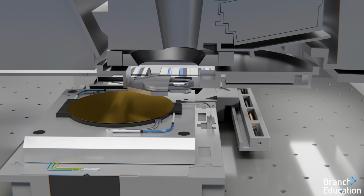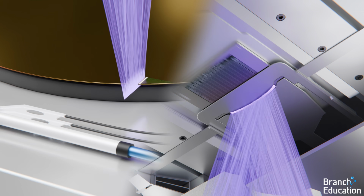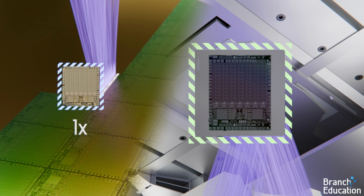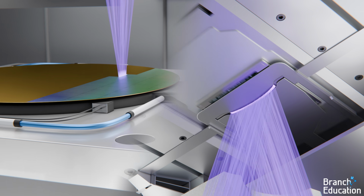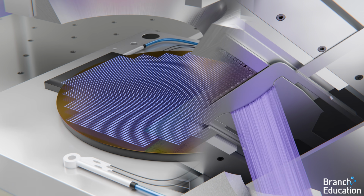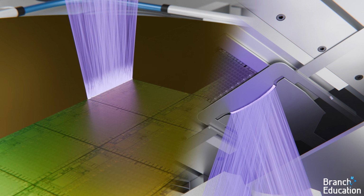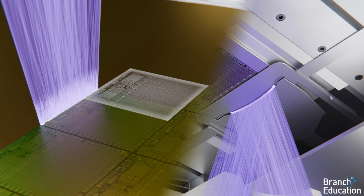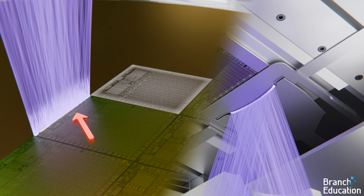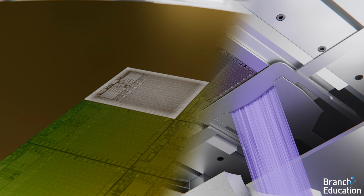EUV exposure station. As the wafer is being patterned, the wafer stage moves in perfect synchrony with the reticle stage, but only a quarter of the distance due to the 4:1 reduction. At the same time, the stage makes nanoscale adjustments using the alignment map so that the new layer perfectly aligns with the previous layer. When the wafer stage moves from one exposure field to the next, it's important that no EUV light hits the wafer, and thus a shutter positioned up here near the reticle stage closes.